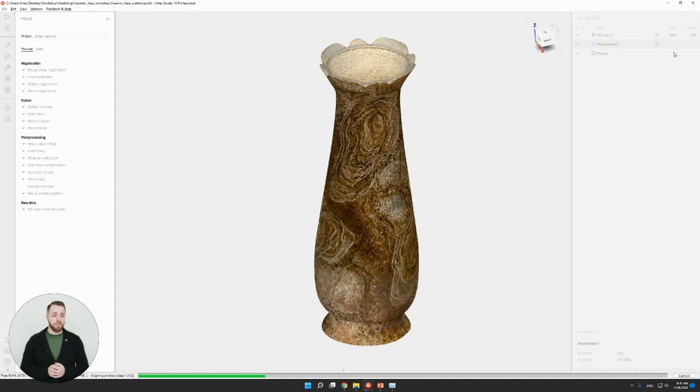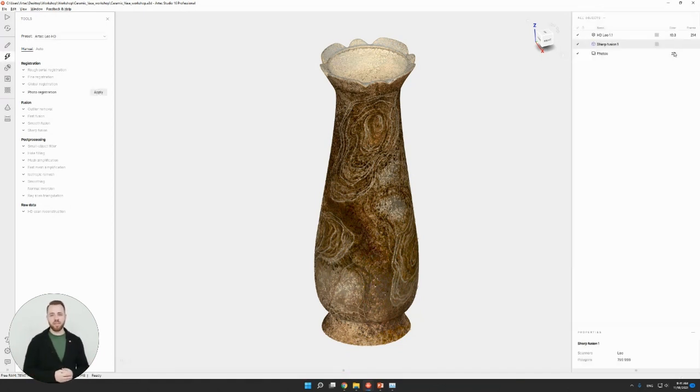And if the error of your photo registration exceeds 5, then you are highly likely to have issues with texturing. Well, texturing will go just fine, but when you assess the quality of your texture, you'll probably see some misalignments. You might notice some blurry areas, or that some areas are actually darker than the other ones. If that happens, your best bet is to take some extra pictures, re-import the entire batch of pictures, so the new ones with the ones that you took previously, and run another photo registration. That's what you do.